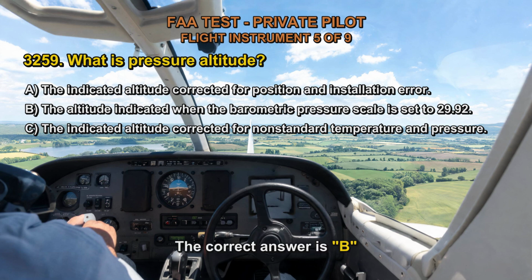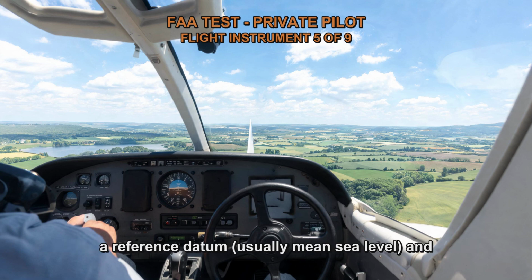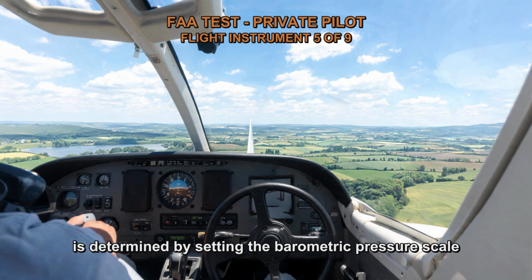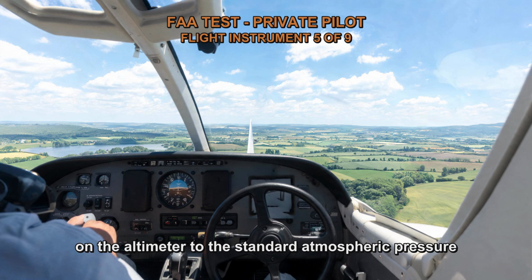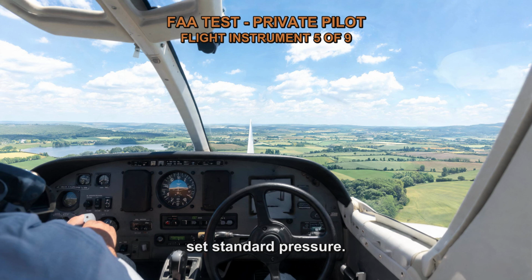The correct answer is B. Pressure altitude is a vertical distance measurement above a reference datum, usually mean sea level, and is determined by setting the barometric pressure scale on the altimeter to the standard atmospheric pressure of 29.92 inches of mercury, or 1013.2 millibars. It represents the height in the atmosphere where the pressure would be the same as the set standard pressure.